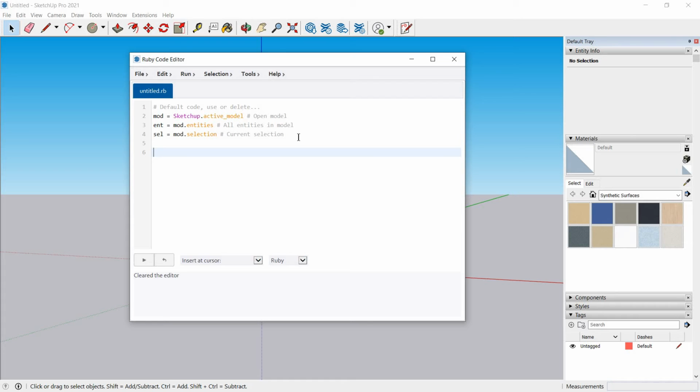As you know, to draw a line we need 2 points. So let's first assign the first point as PT1 and let's assume the coordinates of this to be 0, 0, 0. I hope you know the 3D coordinate system well. If you don't know, the first one will be the X coordinate, the second one will be the Y coordinate, and the third one will be the Z coordinate. Let's assume another point as PT2 and let's assign it to be 10, 5, 7.